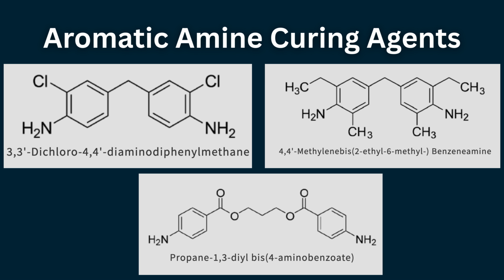Despite these advantages, aromatic amines have several drawbacks that limit their widespread use in adhesives. Most aromatic amines are solids at room temperature and require heating to dissolve or mix with epoxy resins. Elevated processing temperatures may release irritating vapors and increase the risk of skin sensitization or toxicity. Some aromatic amines are also associated with health hazards. For example, certain derivatives such as diaminodiphenylsulfone have been reported to exhibit carcinogenic properties.